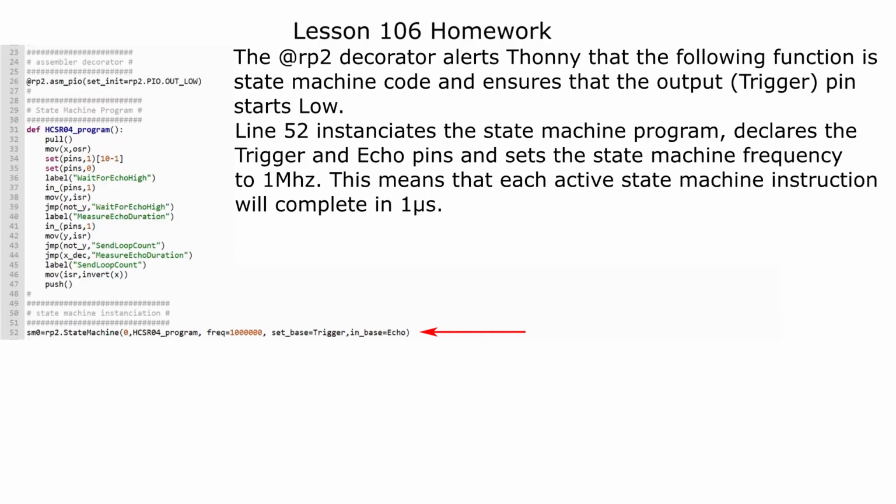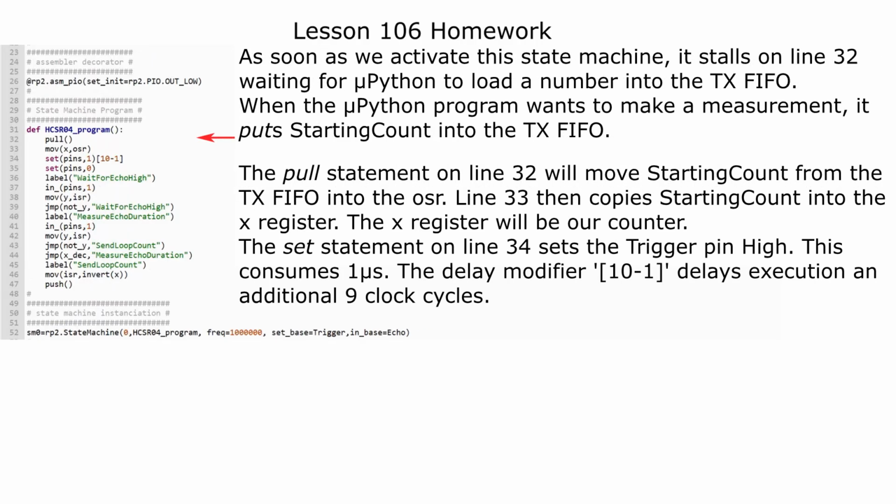This means that each active state machine instruction will complete in 1 microsecond. As soon as we activate this state machine, it stalls on line 32, waiting for µPython to load a number into the TX FIFO.